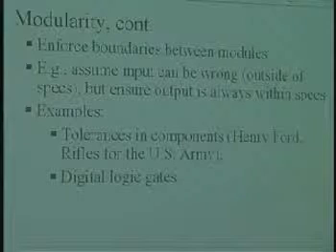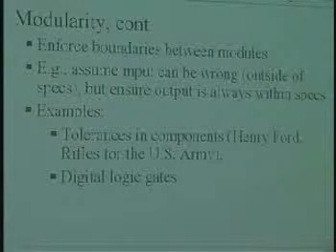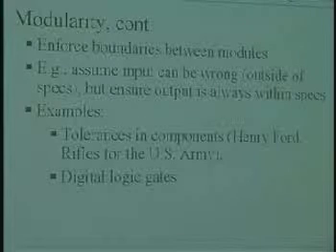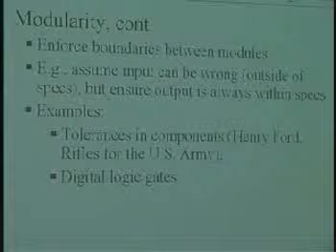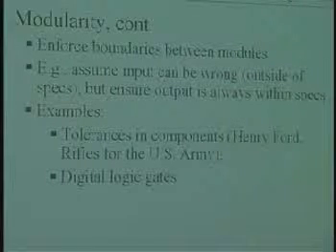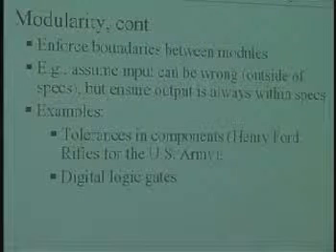So it was very time consuming, very labor consuming. What Henry Ford realized is that if you have the idea of tolerance, where you specify, here's a part, here's the measurements, and here's the allowed tolerances you can have, this then allowed the parts to be interchangeable, and all of a sudden, boom, that led to the advent of the production lines and cars.